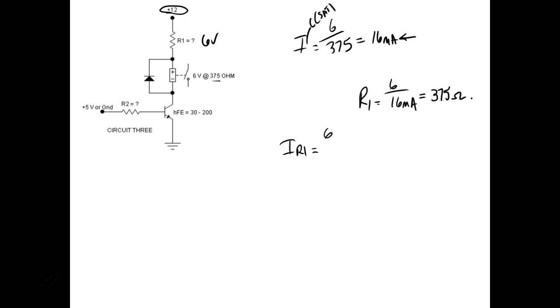You round up to the next standard value. That's all you got, right? With what, 3.9, 3.6? Yeah. So that's normally on these guys. So that is not making sure the transistor saturates. This is the one we got to guarantee that makes the transistor saturate. So if you round it up, if you round it down, that's fine. But I'm just telling you what you would do out there.